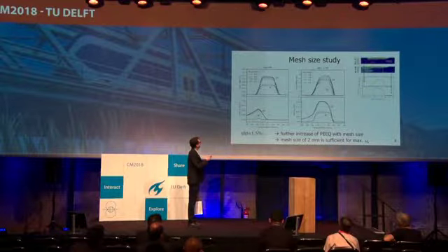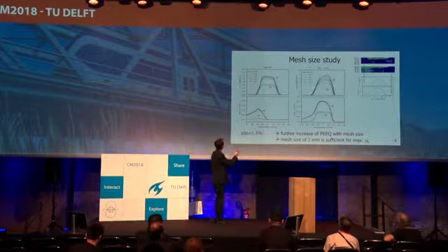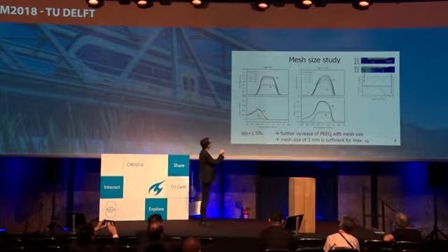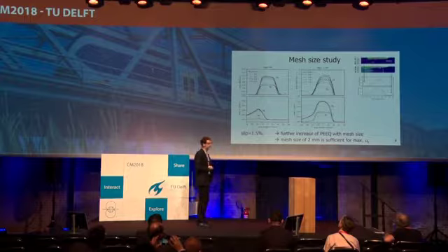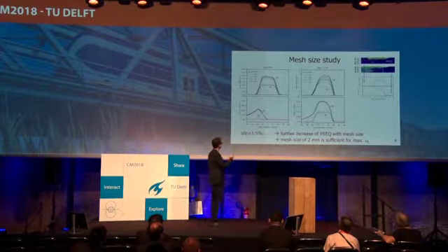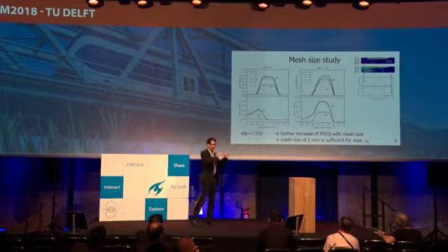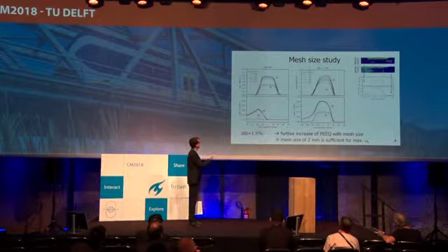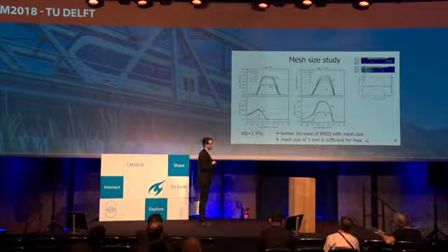Now looking at those different mesh sizes and a certain rolling length, in this case it's 60 millimeters, we can look with a slip of 0% at how uniform our plastic deformations are. In that case, they're quite uniform. And our shear displacements, in that case, they're not uniform at all because we don't have any real slip and it's just an effect on the border.